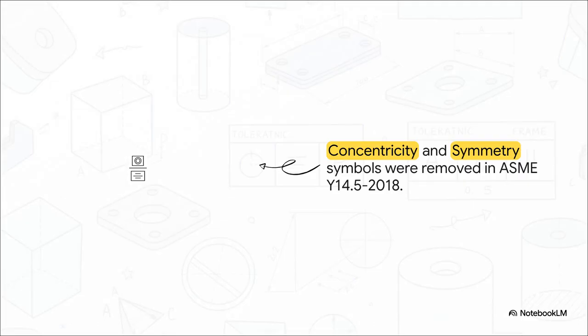Oh, and here's a big one. Please do not use the concentricity or symmetry symbols. These were notoriously confusing and an absolute nightmare to measure reliably because they required inspectors to find theoretical derived median points in space. Actually, they were so bad that the ASME 2018 standard officially banned them. Today, you just use position or profile controls instead. They're much easier to verify and serve the exact same design intent.